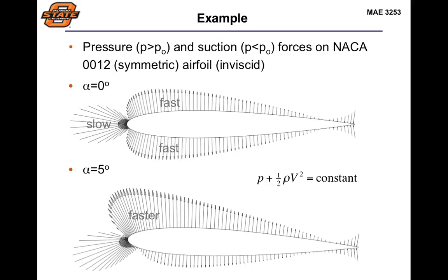When I say negative pressure, we have to be careful about that. We're not actually talking about a negative pressure force itself. This is in relationship to the ambient pressure. So this pressure is a suction force lower than our static pressure value that we have upstream of the airfoil.